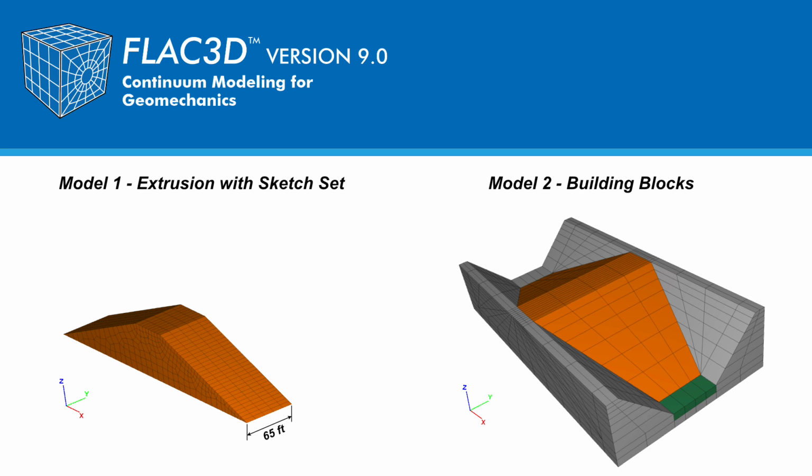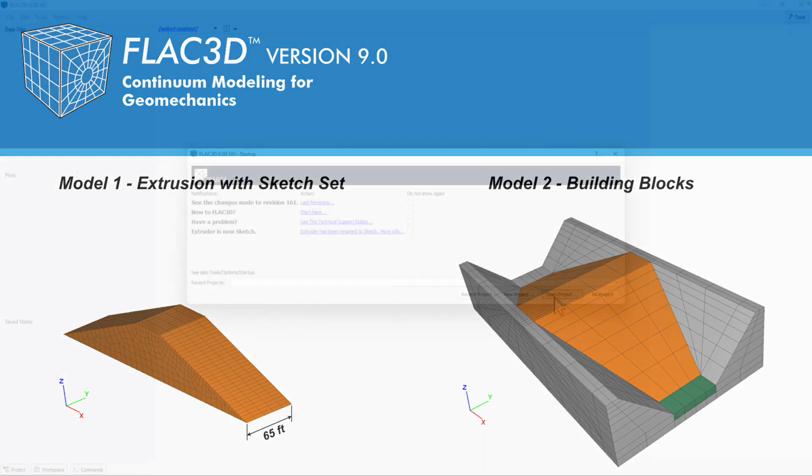In this last tutorial video, the numerical mesh for Model 2, created in the previous tutorial, with modifications of the analysis script for Model 1 given in the first set of tutorials, will be used to calculate the total and effective stress of the embankment with the rock abutments. Please note that for both numerical meshes, the models have been developed to have less than 1,000 numerical zones and therefore can be completed using the free demonstration mode version of FLAC3D available.